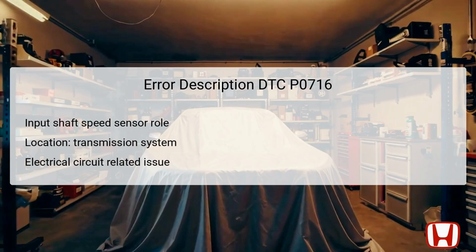As per the diagnostic information, faults that trigger the P0716 code are tied to electrical issues, meaning that the wiring or connections linked to the sensor may be compromised. It is important to note that any mechanical problems within the transmission itself would not cause this specific DTC.